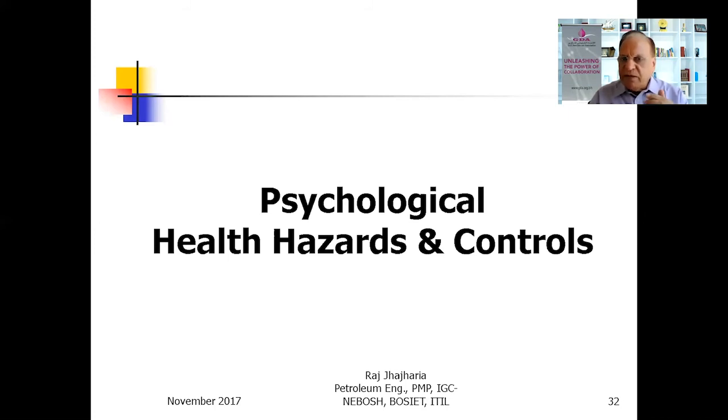Third thing is, every extinguisher needs to be periodically tested, and the next date of the testing should be marked on the calendar, on the body, or on a tag attached to the extinguisher. You must make sure that it has been tested recently, and also its test validity period is still available. So you are not using an expired extinguisher, or one whose seal is broken, or in case of dry powder, one that has become a cake. So remember these things.